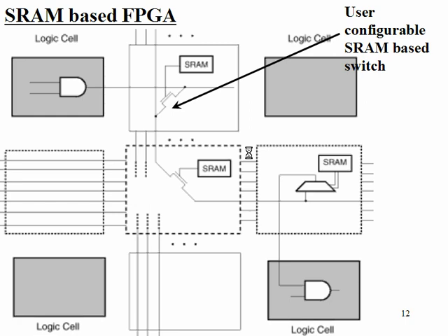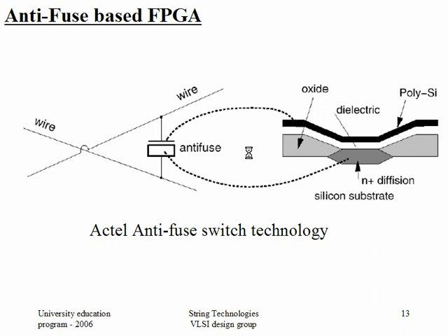For example, you have implemented a logic where these two need to be shorted. So an SRAM bit will be 1. That is exactly what my tools will do. When I give some VHDL code and say Spartan 3 FPGA, it knows how to configure the Spartan 3 FPGA: which MOSFET to open and which to close to realize the logic. That is exactly the job done by the synthesis tools. Got the point? This is SRAM-based FPGA, very simple to understand. Because I am using SRAM, which is volatile, my SRAM-based FPGA is volatile and it is reprogrammable. That's all.